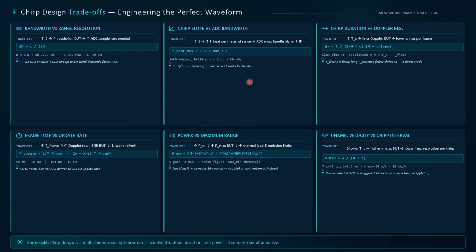So basically that needs to be in the digital domain, right? You're going to convert it from analog to digital, after that mixer over there. For the ADC to perform the job, it needs to have a higher frequency, like two times higher than that IF. So it's very challenging, you have to make the selection properly, or else the burden will be on the ADC.